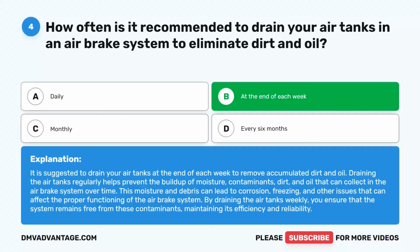This moisture and debris can lead to corrosion, freezing, and other issues that can affect the proper functioning of the air brake system. By draining the air tanks weekly, you ensure that the system remains free from these contaminants, maintaining its efficiency and reliability.